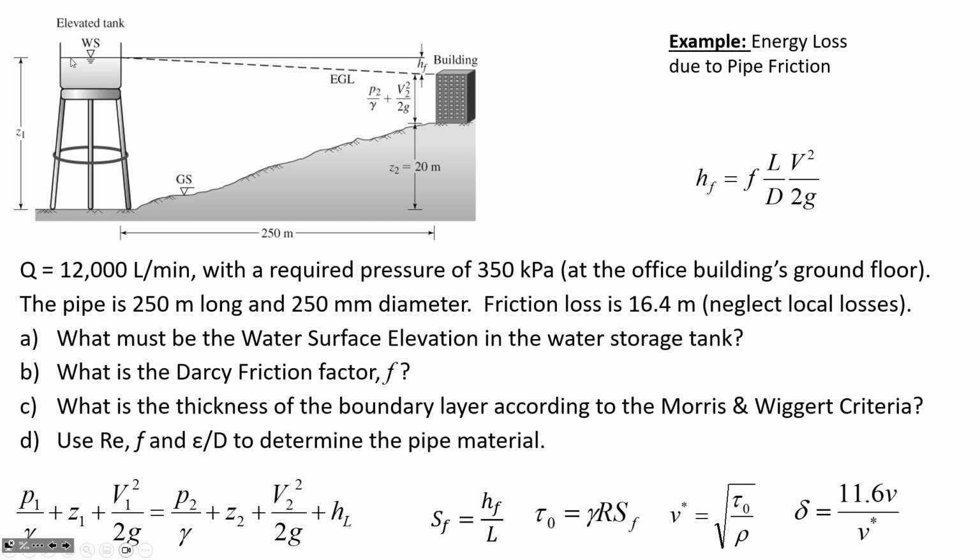Would it just be atmospheric pressure? Just be atmospheric pressure. So now let's ask ourselves, are we going to work this problem in terms of absolute pressure or gauge pressure? Gauge pressure is we're saying, let's have the atmosphere be 0 as our starting scale. If we're measuring pressures in terms of absolute, then we'd use like 101 kilopascals as atmospheric pressure. Let's use gauge. That's what we'll typically do, is we'll just take for granted that atmospheric pressure exists, but all the pressures we're going to measure are over and above atmospheric pressure. So by that regard, we're just going to say that the pressure at 1 is 0. So P1 is 0, so we're going to cancel out that term.